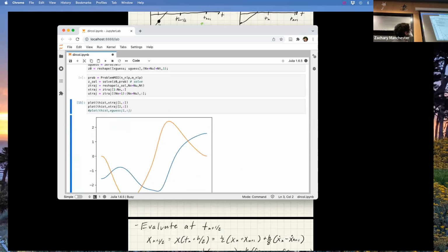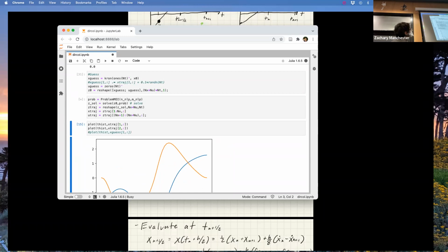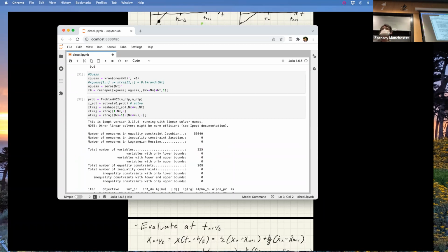And that's going to take a minute. I think I ran this before, so we can probably just look at it. It's kind of slow. Exactly. The whole point of us doing this direct collocation method in the first place is that it's more stable. We're trying to optimize trajectories, right? That's one of the reasons. This is one of the two major options. You can do DDP stuff, you can do direct collocation stuff, and there are trade-offs. We'll get into the details of the trade-offs. This is one of the standard algorithms, and there are reasons to just do this. In general, the DDP stuff and this stuff are on par with each other, and depending on your application and what you're trying to do, one or the other might be preferable.